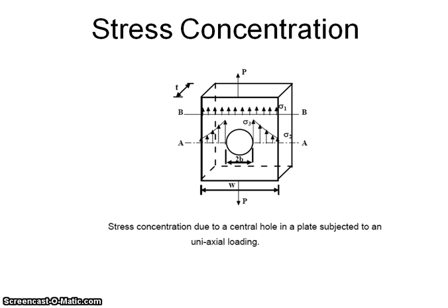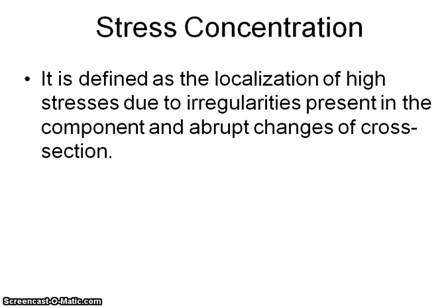This is done with the help of the stress concentration factor, Kt. Kt is the highest value of the actual stress near the discontinuity divided by the nominal stress obtained by our elementary equations for the minimum cross section.